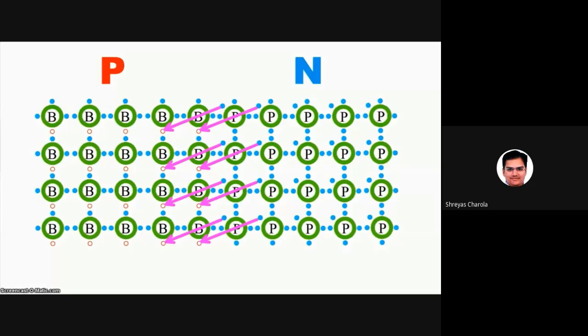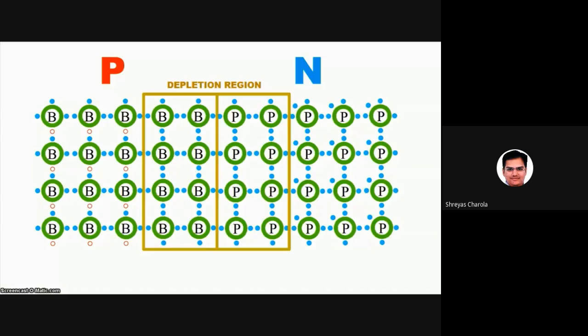At the border between p-type and n-type, the extra electrons from the n-type silicon jump over into the holes in the p-type silicon and fill those holes. Because of this, a depletion region forms and creates a barrier between the two crystals. There is a layer of p-type silicon that now has extra electrons filling its holes. Remember, this area used to be neutrally charged. Now the electrons make this area have a negative charge.